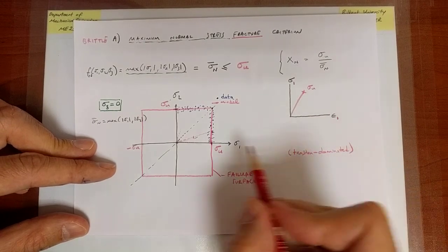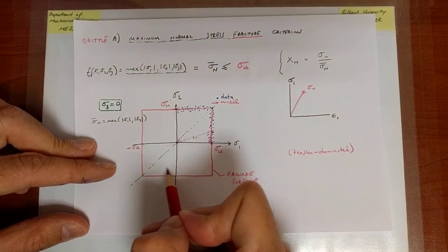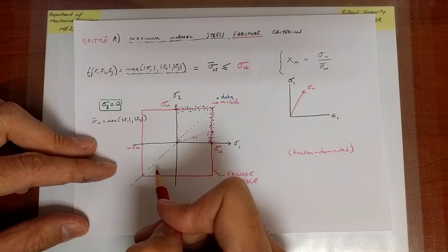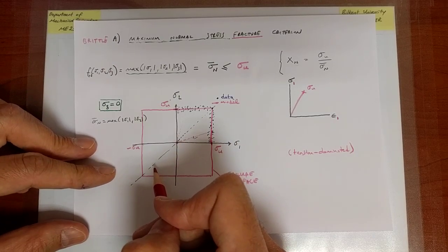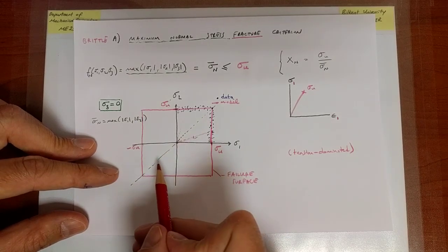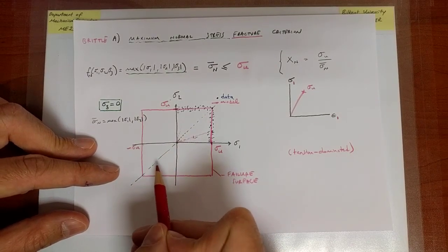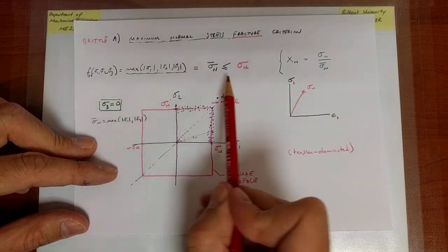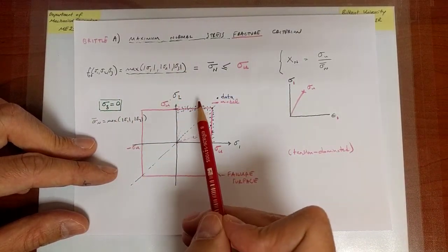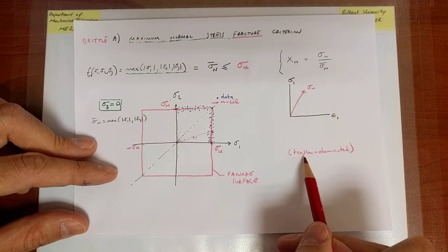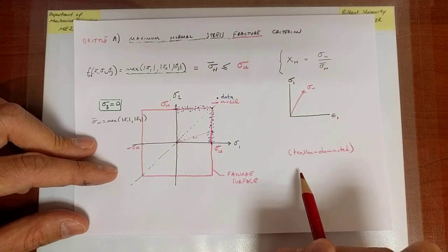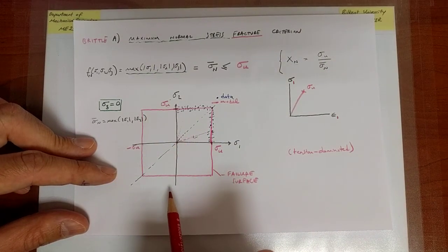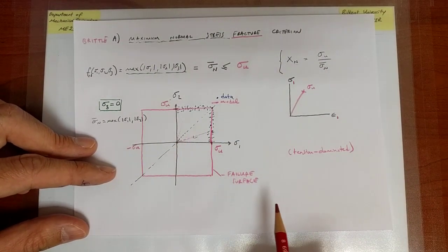Because if we lie in a case where it's compression dominated, let's say in that quadrant, we would be over conservative. I don't know how conservative I am. Essentially, strictly speaking, I wouldn't be making a correct prediction, and therefore we want to avoid a misleading prediction. So when I apply the criterion in this simple form, I want to first also check that indeed I am in the tension dominated scenario. If not, I may want to use a better model. Are there better models? Certainly, but we're not going to cover them.